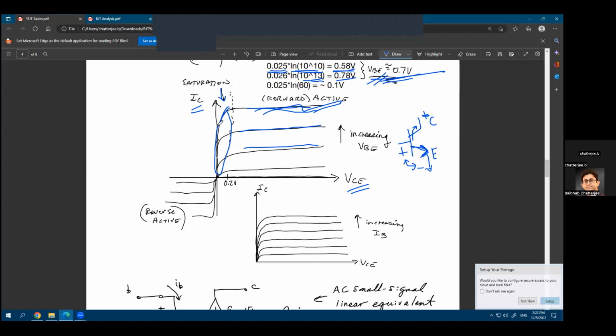That's what is happening in this region. So what is actually happening is that inside the base, you're getting a saturation of carriers. So your base is getting saturated with carriers. There are so many carriers inside the base. And by carriers, I mean the majority carriers in the emitter or the majority carriers in the collector side. There are so many carriers inside the base that the base is getting saturated and the collector is not collecting enough of them. That's what is happening in this region.